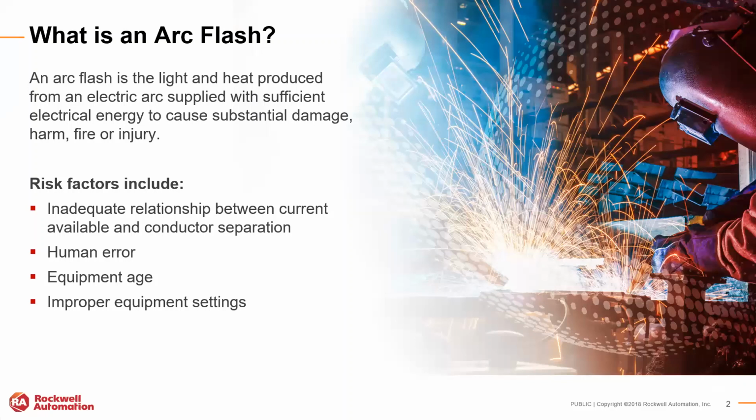There's a sound blast that can damage hearing, resulting in temporary or permanent hearing loss. And then the flash itself from the arc flash event can result in temporary or permanent blindness depending on the severity. So of course all these various side effects, depending on the size of the arc flash event, could result in injury to personnel, potentially serious injury, or even possibly death.